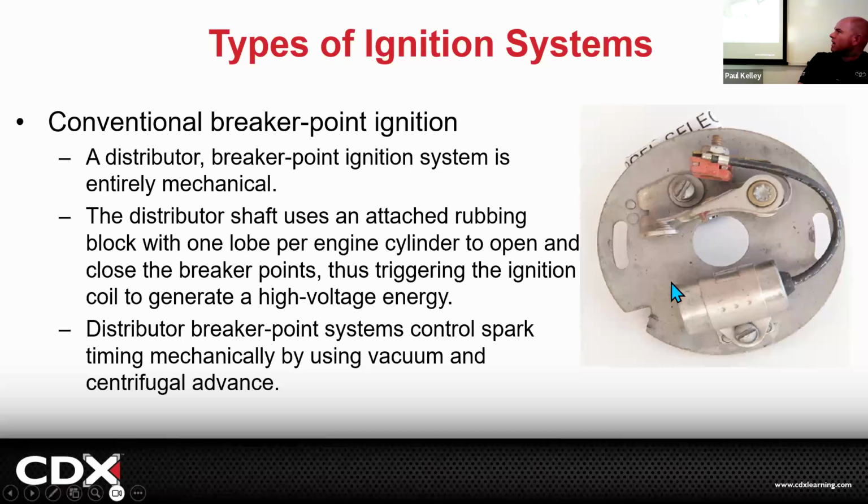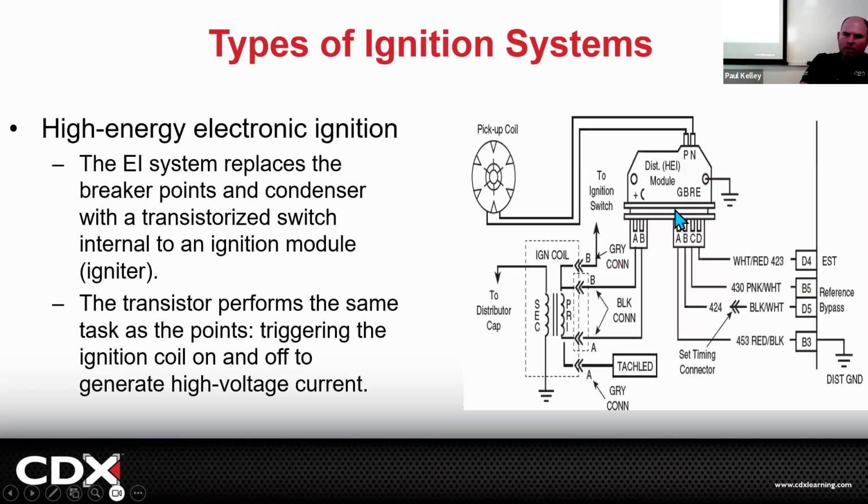That's kind of what I was showing you right here, your breaker point system. That's literally the breaker point. You could replace these little points, and right in here, it would have a spinning part that's splined to the cam that would bump it open. All right, cool. That's pretty much the jam.